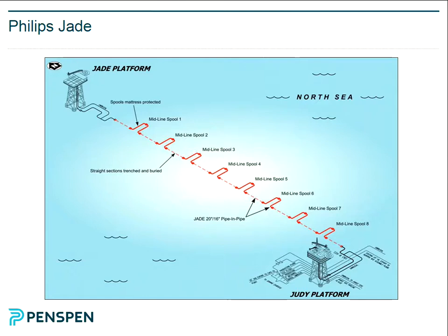So it's a steel inner pipe, obviously, and then the outer pipe is also steel, and in the space you have a vacuum or very low pressure, and in that vacuum you have a very, very good insulator. Because good insulators are not mechanically strong, to be able to build a pipeline where you have an insulator which is conventionally installed is quite difficult. So when you want a very high amount of insulation, you have to go to a pipe in pipe. So this is a pipe in pipe system.